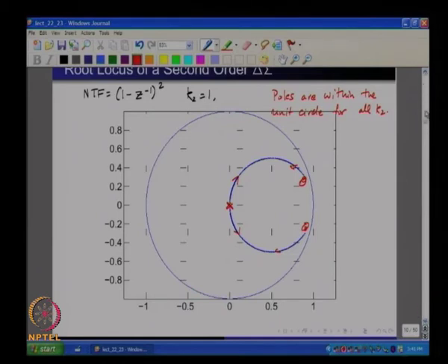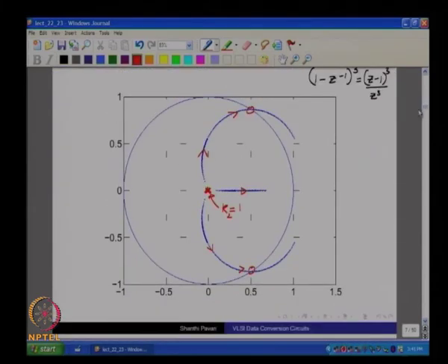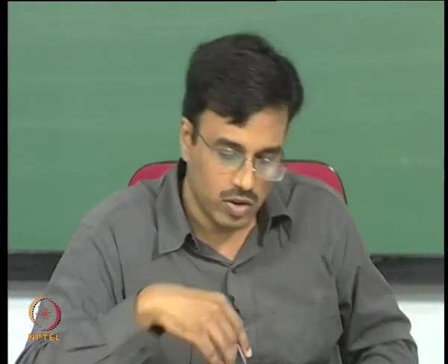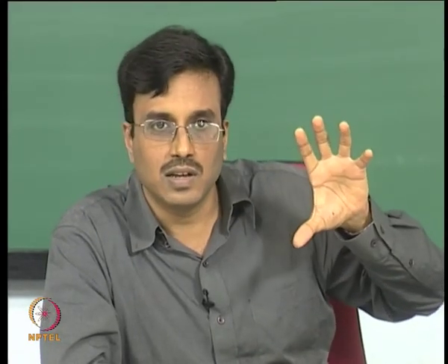In a third order modulator, for example, when the modulator becomes unstable, the variance of the quantization noise, or rather the input to the quantizer, becomes so large that you are deep inside the unstable region, that is way outside the unit circle, and making the input 0 does not really help, because you are still outside the unit circle and these state variables are still growing exponentially.